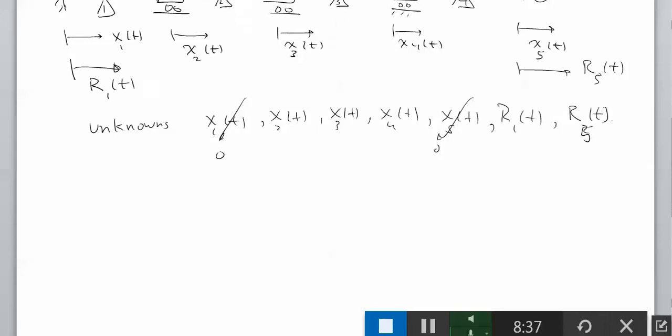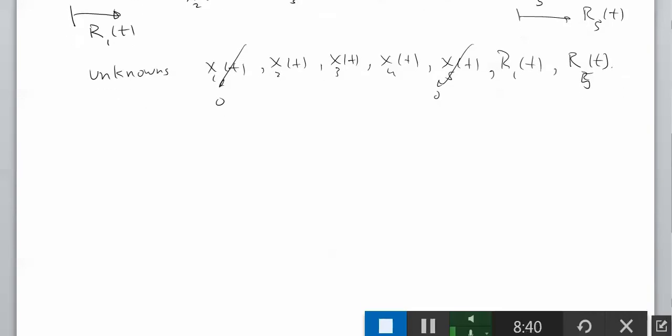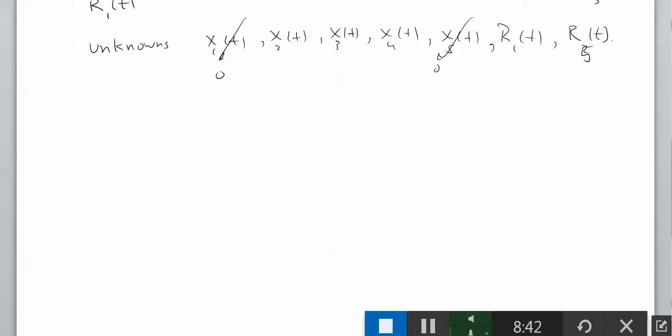Now in order for me to set up this problem, what I would like to do is to isolate a generic spring element like so. So here is the spring element. We can call it element E with a stiffness of Ke. So on the right side I have a node, on the left side I have a node, but since this is a generic one, why don't I call this thing the left mass and this the right mass?